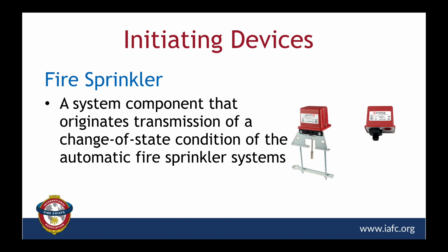Another type is a dry type sprinkler system in which the pipes are filled with air, pressurized air or nitrogen rather than water. Now, these pressure systems are typically used where winter temperatures fall below freezing, and it's necessary to keep the pipes dry until the water is needed.